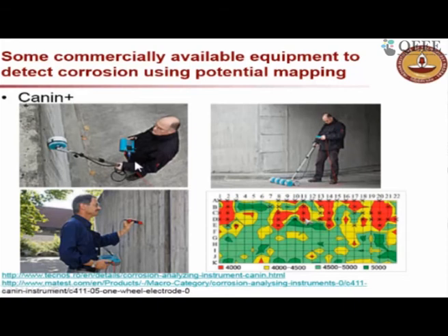But when the concrete starts getting carbonated, the pH level drops, and once the pH is below 9, it can actually start corrosion. And in the other case, if chloride is reaching, even without the reduction of pH, you can still have corrosion if the chloride level at the steel surface is above the chloride threshold.